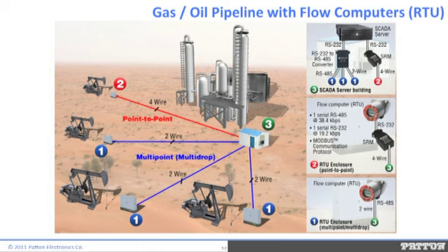The flow computers in the application diagram offer both RS-232 and RS-485 electrical interfaces, having a maximum data rate of 19.2 kilobits per second or 38.4 kilobits per second, respectively. The SCADA server, on the other hand, has only an RS-232 interface. So for a point-to-point connection, modems are connected at each end of the link, one at the flow computer, the other at the SCADA server.